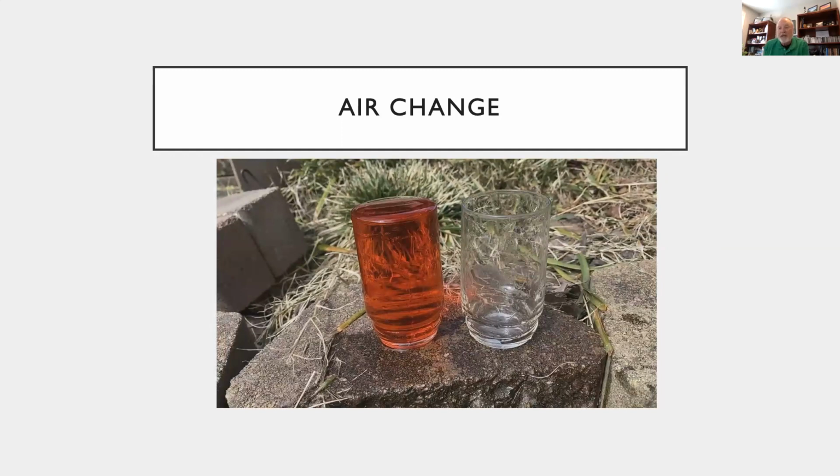Well, it's the same thing in our buildings and our rooms, right? One air change doesn't really do anything. To get all that out of there, I didn't try it, I probably need 6 or 8 glasses of water to get it pretty clear where you can't tell that it was tinted, right? That the Gatorade's gone. So one air change per hour really doesn't do a lot of taking things away. We need to be more strategic in how we take things away that we want to get rid of.